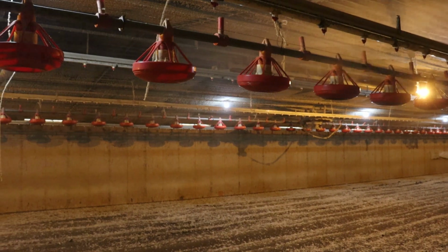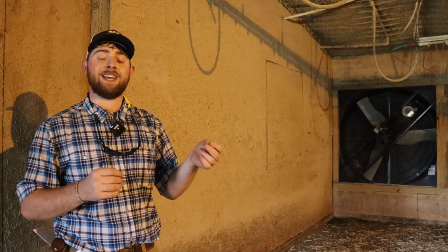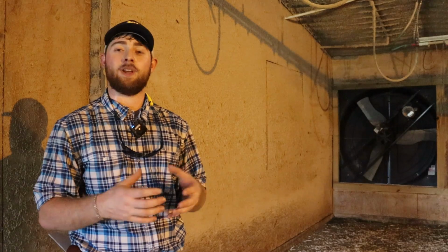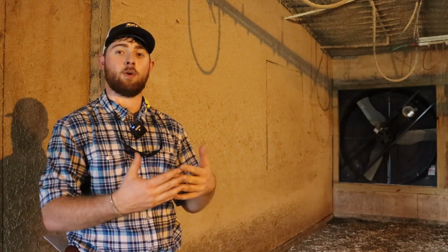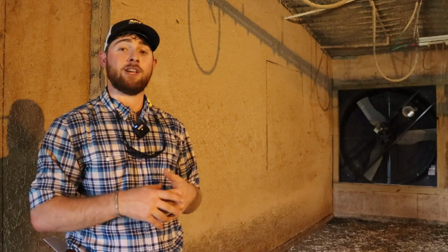Heating that air is important because for every 20 degrees we heat that air, we're going to cut its relative humidity in half. The whole purpose of exchanging our air in our houses is that air acts as our sponge, and the drier we can get that sponge, the more water we can pull out of our house. The lower the house's internal humidity will be, the better the litter conditions usually are on our floors.